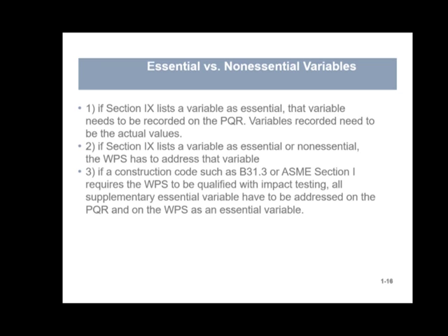And once again, let's say you did a weld procedure and you didn't use post-weld heat treat. You don't list NA if you didn't do it. You list none. N-O-N-E, none. This is one that gets a lot of weld procedures kicked back. If you just remember this, it'll save you a lot of trouble. And if something is NA and you put none, nobody's going to kick it back for that. You're just telling them none.